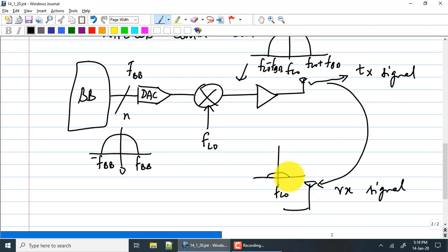In the analog ICs course we have started looking at noise. As you know, every circuit that you use has some noise. Today we saw that it's characterized as an input referred noise. So imagine now the signal has become so small, on the order of microvolts, let us say, and the noise of the circuit may also be of that order or only slightly smaller. You need to make sure that the signal is much larger than the noise itself. So the first thing you need to do is send it through an amplifier so that the signal becomes as large as possible while adding as little extra noise as possible.